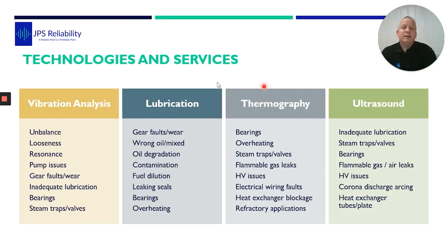Again, a great slide which shows that we don't just use vibration analysis or lubrication or ultrasound. We use them all. Each particular technique, for a particular failure in a particular application, can be an indicator, so it can indicate it's failed before the system functionally fails, or it can be a predictor. In this case, it was an indicator, and we can predict now. We know what level it is, and we can now trend it. Also, it shows ultrasound would have been just as amazing in this situation, with a high sample rate and the ultrasound waveform, and it would probably have been even clearer.